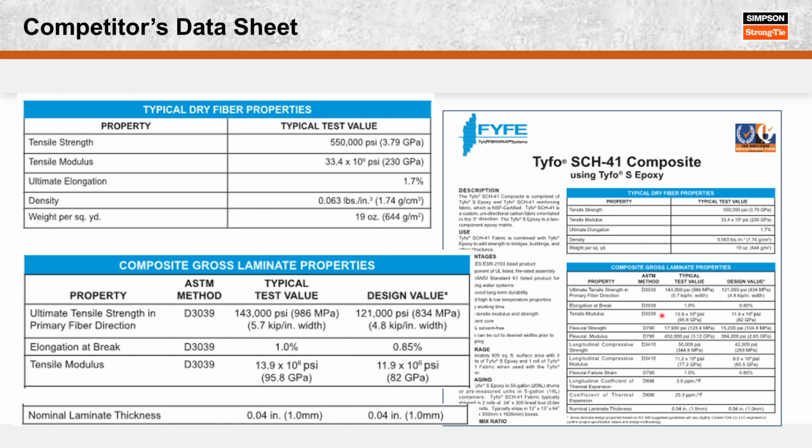I think on Chief's list was show our competitors' data sheets, maybe. It's a little bit different than the way we show things. Some of our competitors show basically the minimum stiffness per inch on their data sheet, and that's something that we don't show now that I've been considering adding, because a lot of our competitors are showing that now. But if you know our values, like Griff has mentioned before, our modulus is 14.2 and theirs is 11.9.